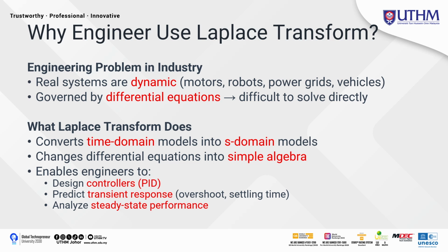So what the Laplace transform does is very powerful. It converts the problems from the time domain into the S domain. Then the differential equations become very simple algebraic equations. So this allows the engineer to design controllers such as the PID controller, predict how fast a system responds, and check the overshoot, settling time, and steady state behavior.